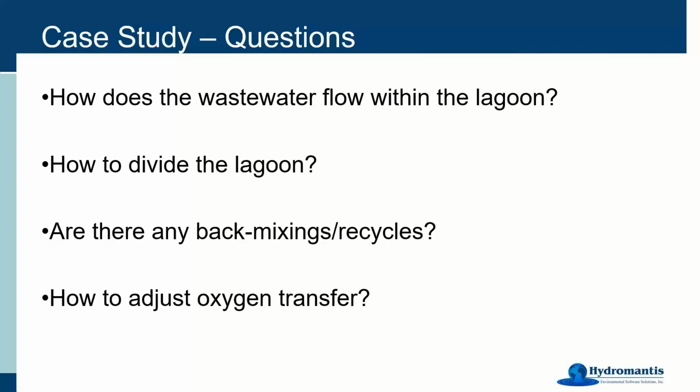The Langley wastewater treatment plant uses floating mechanical aerators. So we should expect the oxygen transfer rate to be higher in the area adjacent to the aerators, and as you move away from the aerators, the oxygen transfer rate should be lower. So these are some of the questions that we need to answer when modeling the lagoon system.